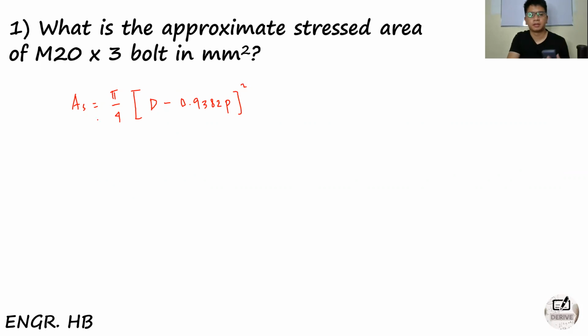If your diameter D is in mm, the bolt major diameter, and your pitch is in mm, then your stress area will be in square millimeter.